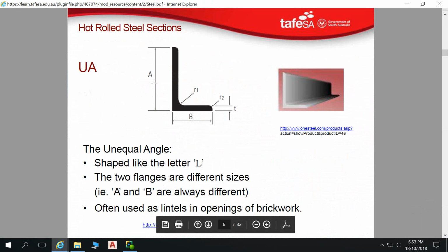So, and then our angles. Angles are used a lot in this hot rolled steel framing as well. Tonsley is a fantastic place to see these elements in use. If we look out the window here, we've got universal beams, we've got equal angles welded on as well. This great big column here is two PFCs welded together to create a column. So this is our weld up here.